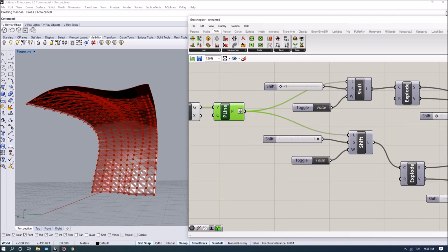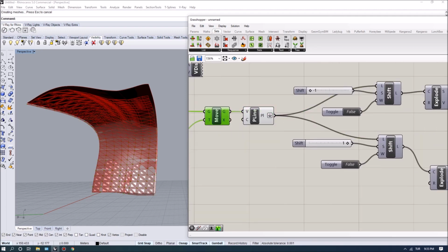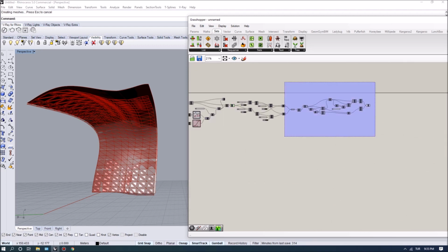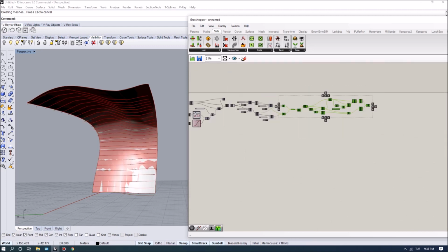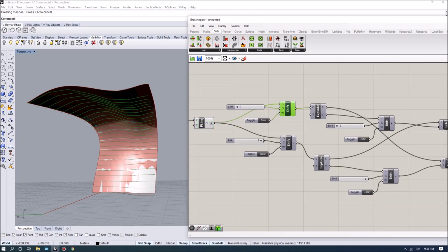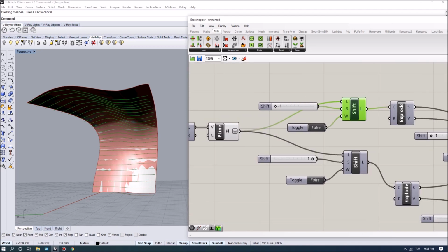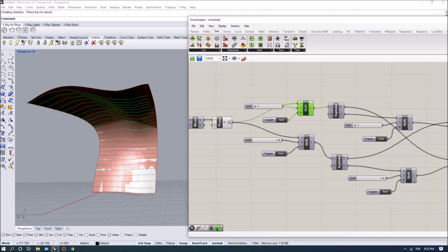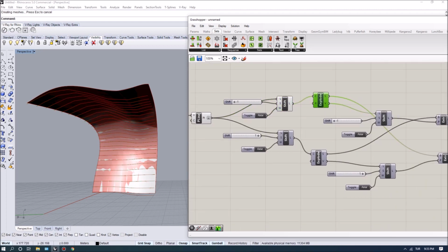And then the data comes in as rows, so I first converted them into polylines. Let's go back here to the second step. I started with polylines, and the first step was to filter them. I created two shifted lists. Basically we want to get a list without the last element, and a list without the first element, so that's how the data will match each other.